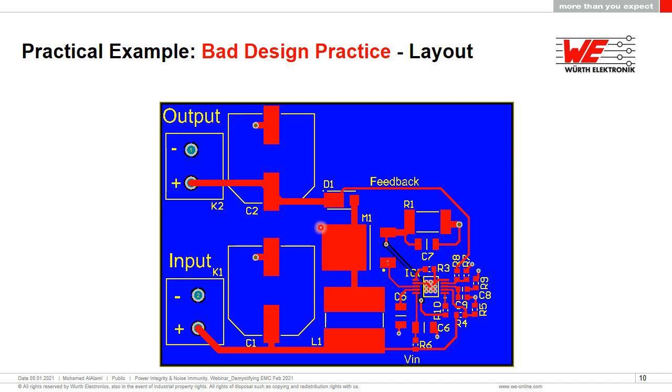You can consider that maybe some younger people, some of the design engineers, do not necessarily have the experience on how to lay out and track and how to minimize these loops and how to look into the EMI aspect of laying out and placing a power supply. So sometimes you end up with a less than desirable layout and tracking practice. So that's one aspect in here.